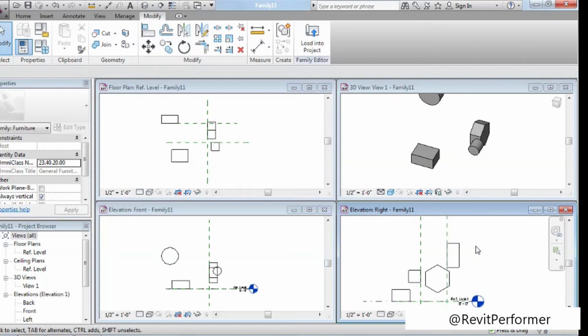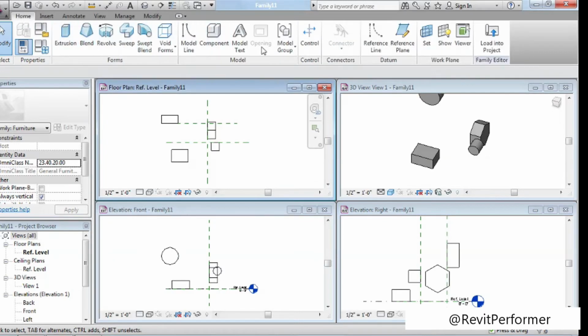Reference planes have direction. And this is a little bit of a challenging concept, unfortunately. In general, it's predictable which direction the reference plane is going to go in for the ones that you create yourself, because you're going to click and place the 2 points that define the reference plane. So if I start back here in Plan View and I go back to my Home tab, click on my